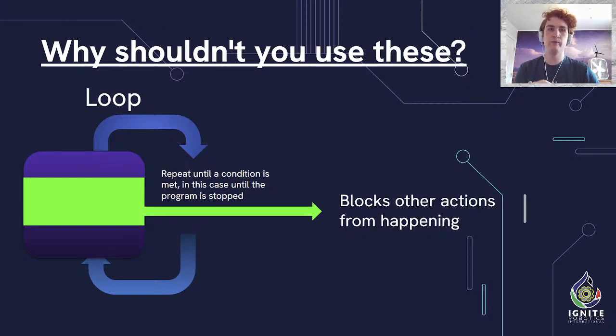So when you try to update something, it'll take significantly longer to update because the program's busy doing something else instead of reading your inputs. This is not ideal for having code that works well. There's actually quite a few problems where you can press forward and then you click a button and then you just drive into a wall because your robot never updates the values that it sets to the motors because it's trying to do something else at the same time.